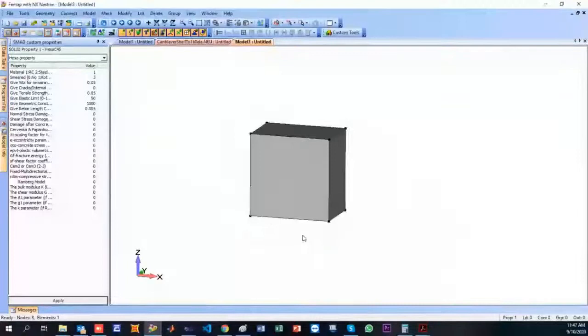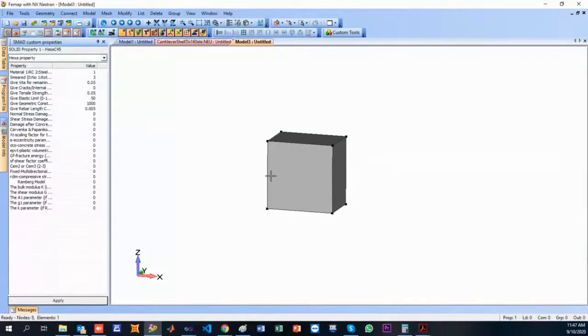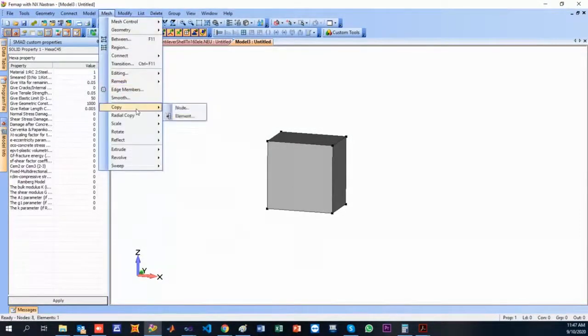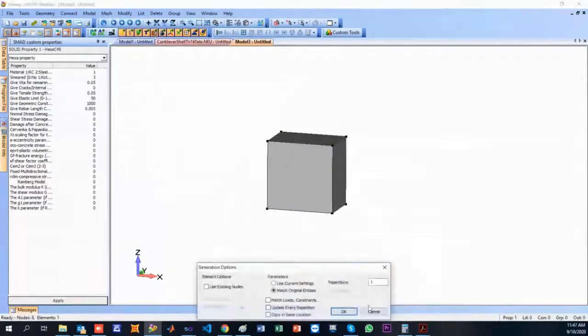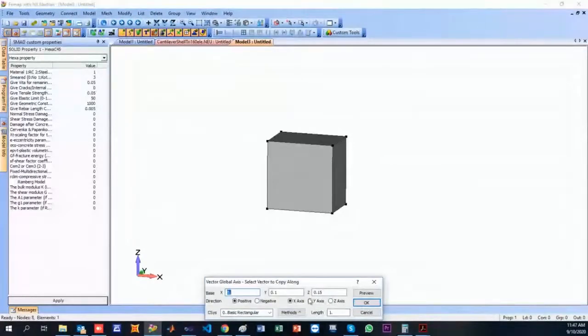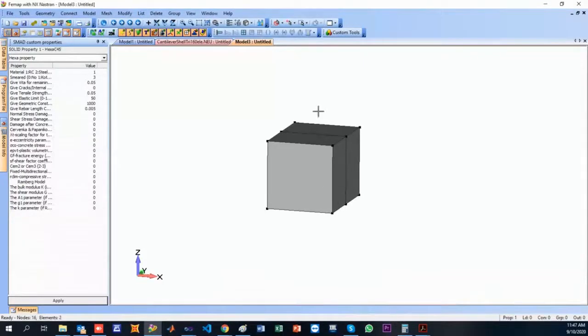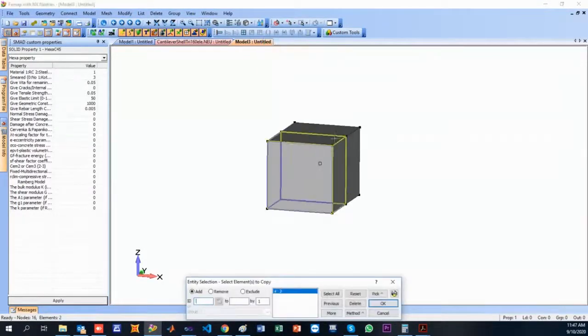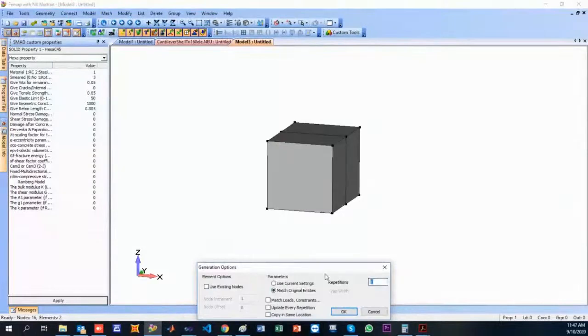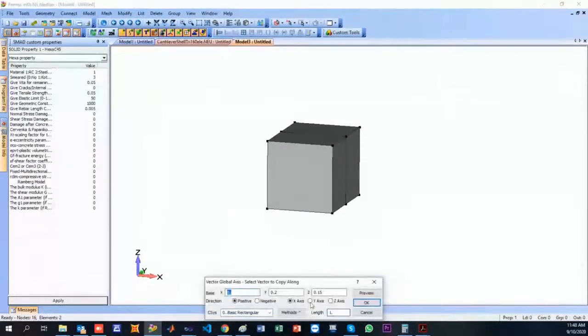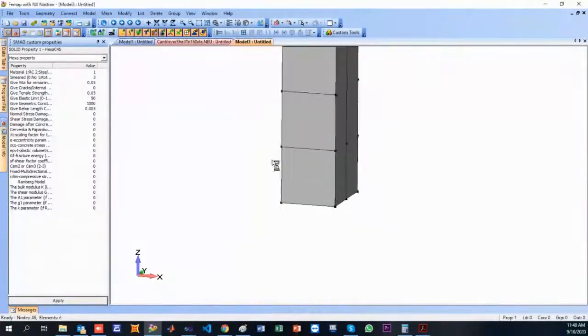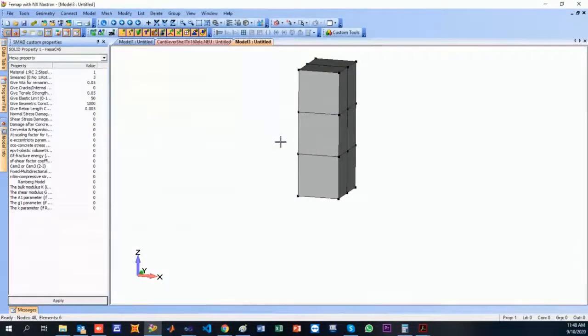So there you go. Then, if this is one element, then I will start copy pasting, mesh copy element. How many times should I copy it along the X-axis, or I will copy that once along the Y first, just to create the first section. Okay, 0.1, and then along the Z 2 times. Okay, 0.15 cm, there it is. So this is my first part.